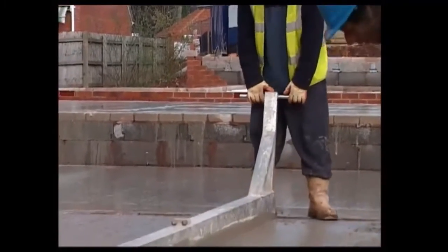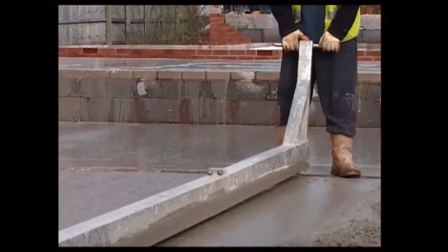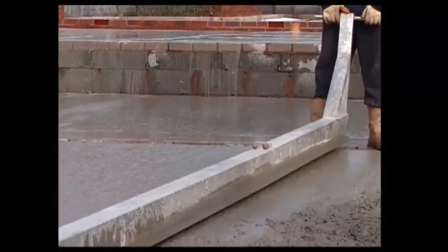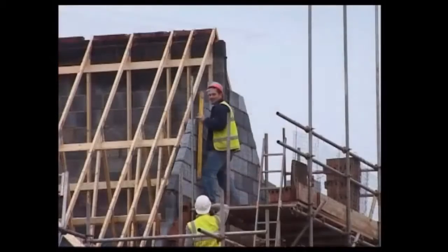The concrete will set in a few hours and achieve its full strength after a few weeks. In hot weather, it can dry too quickly and crack. A temporary layer of sheeting will control evaporation and slow down the set. In cold weather, Hessian or special quilts can protect the concrete from frost.